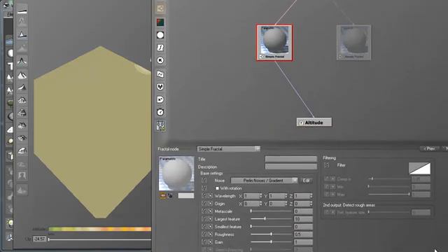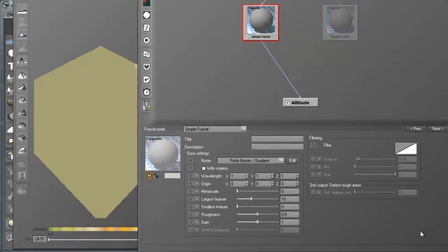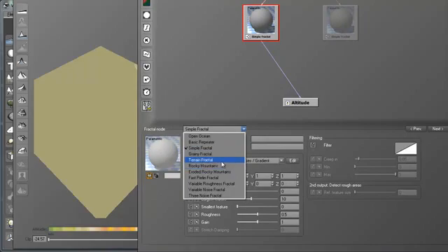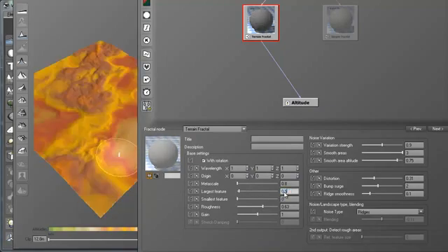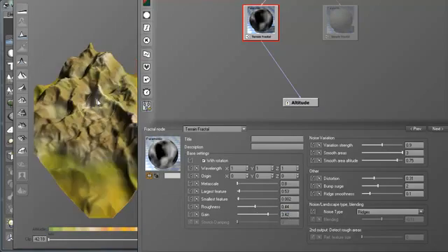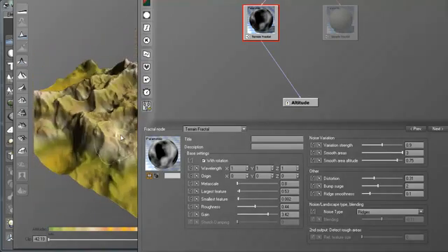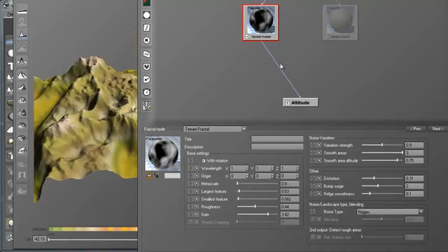Select the altitude option, and now in these presets we're going to pick terrain fractal. Now I've prepared some values so we get a nice terrain here. So I'm just typing my values. Okay, this kind of terrain I want to achieve. This is for the first one.